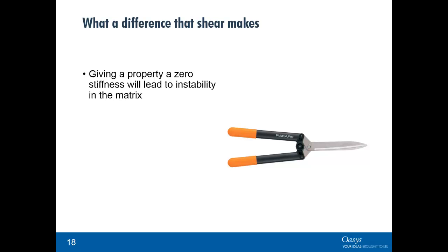On the other hand, if you're doing a grillage model and you want to prevent torsion in the grillage, it's best not to put the torsional stiffness, the J value, to 0, but maybe put something very, very small. So there's minimum insignificant torsional stiffness, and therefore the bending stiffness takes over.